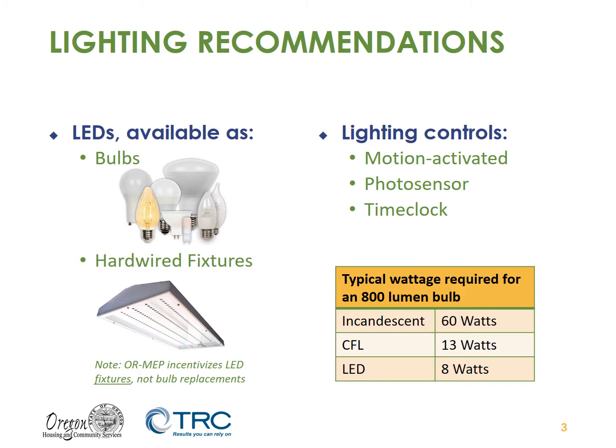Controls are also crucial for lighting savings in common area or exterior applications. Exterior lighting should be controlled by photocells or atomic clocks, while motion activation may be preferable in interior spaces. For spaces that should maintain a minimum level of lighting, such as hallways or garages, bi-level LED fixtures can dim down to a pre-assigned set point, typically around 20% power, until they sense movement, then turn up to 100%.